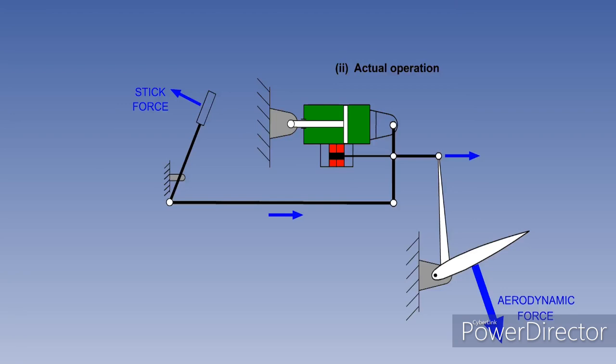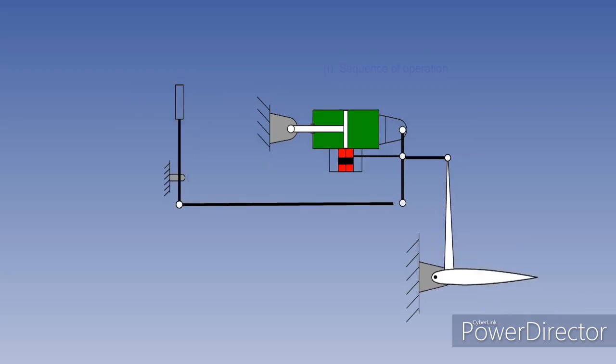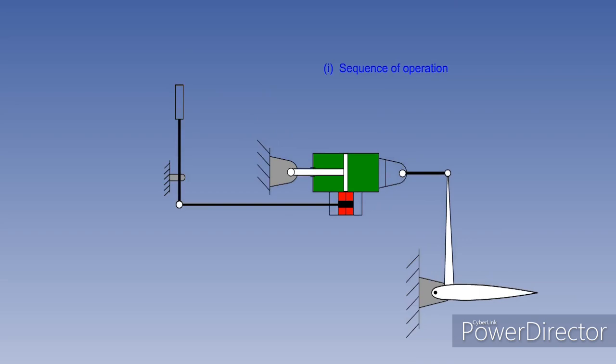If hydraulic pressure is lost from a power-assisted flying control, the pilot would still be able to control the aircraft, but with significantly higher stick forces. Power-assisted flying controls, therefore, do not require a separate manual reversion system. If the speed or size of an aircraft dictates, a fully powered system will be fitted.